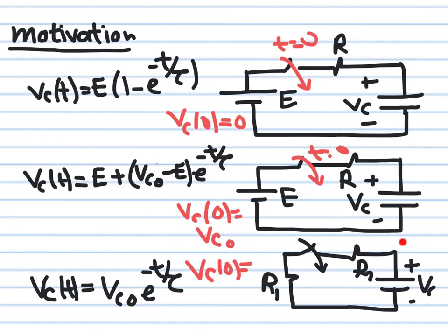One other example we tried before is a capacitor that's charged, and then you connect it to a resistor or 2 resistors. Now this one is connected to R1 and R2. It will start to allow current to go through in the circuit, and it will be losing its energy gradually and slowly. Its voltage will be decaying with time, and you see that the expression here is VC naught e to the minus t over tau, and tau is the time constant equal to the total resistance multiplying C. So tau here is R1 plus R2 times C.